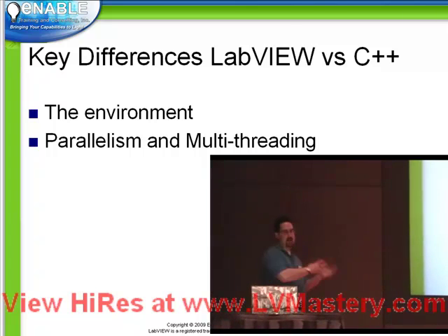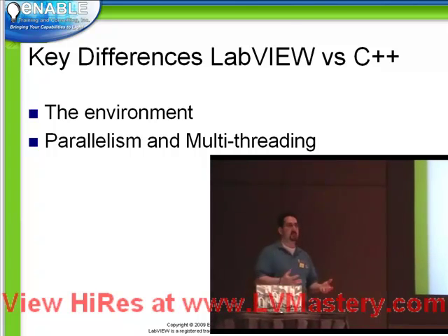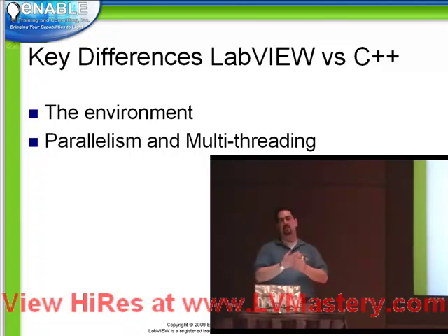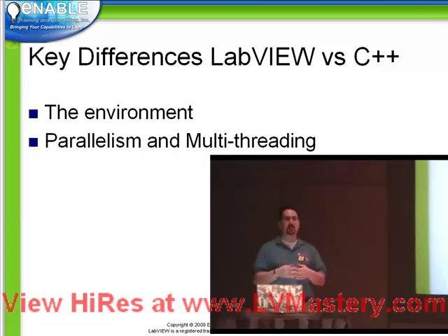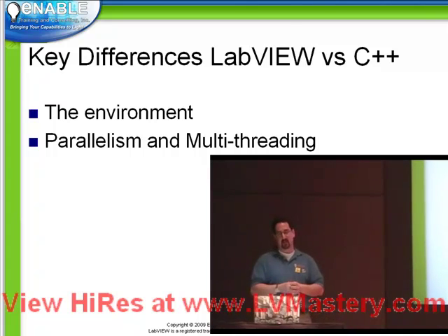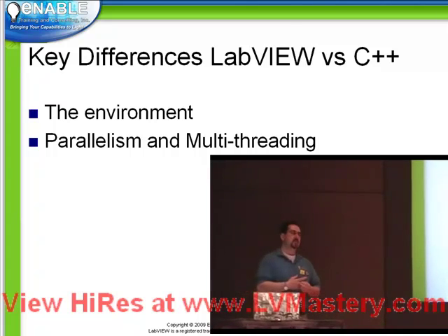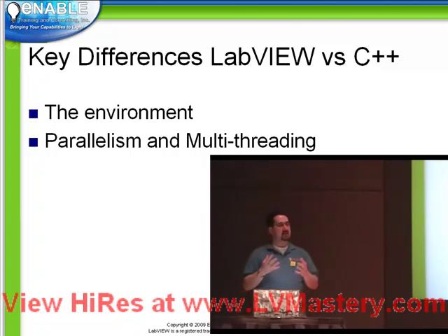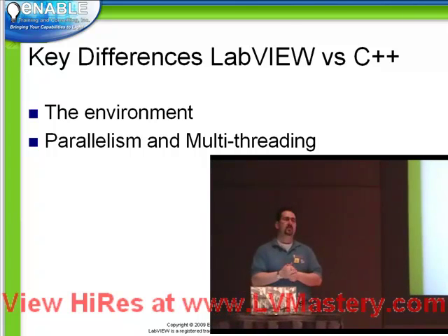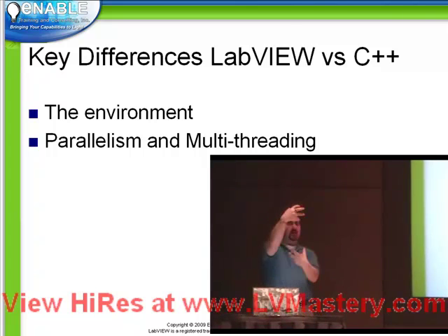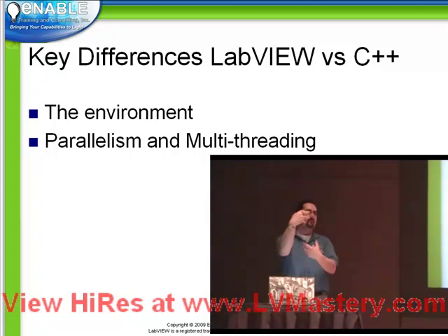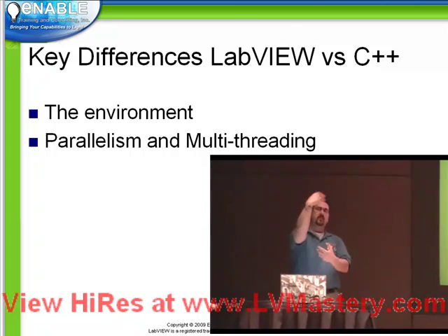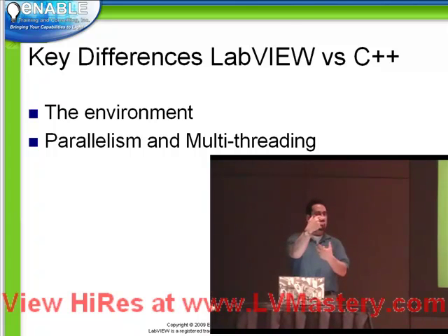So what I'd like to point out now are some of the key differences between LabVIEW and C++. The environment is obviously one. We saw that, it's graphical, there's very little typing, navigating doesn't involve accessing subroutines the same way you do in the C++ environment. Parallelism and multi-threading. LabVIEW has a neat side effect of the data flow paradigm, which is if two things don't have a wire connecting them to each other, they run at the same time. So that means if you want to start motor A and start motor B, they'll start at the same time.